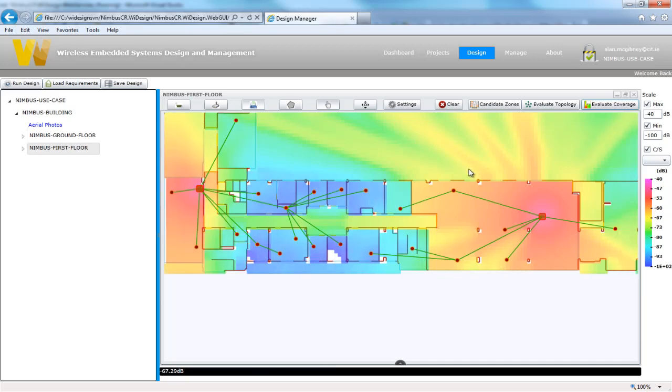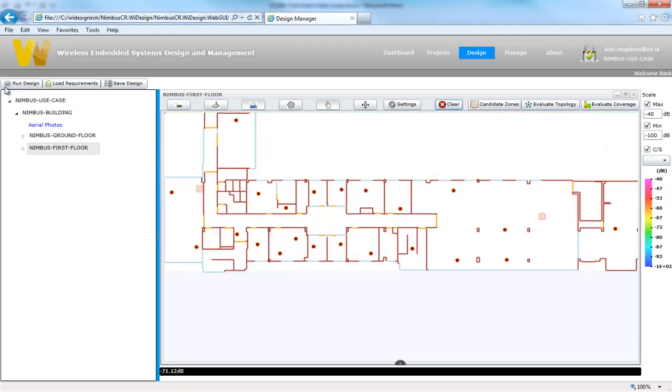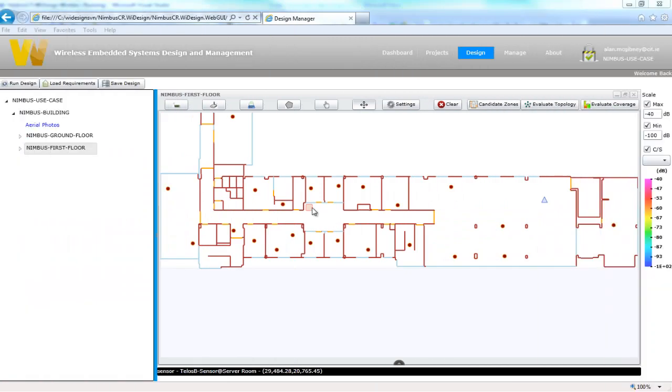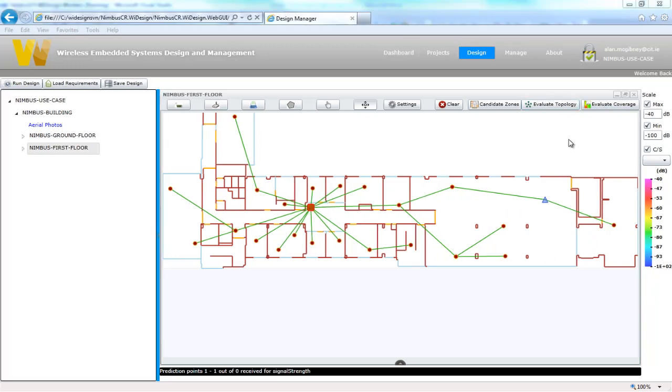Even with the tool, manual tuning of device placement can be a difficult process, especially if the environment is large. Therefore, the Wireless Deployment Planning tool provides an automated device placement algorithm which will optimize the number and position of gateway and repeater devices driven by the placement constraints defined by the user. In this example, the results of the optimization process propose that a single gateway and the addition of one repeater is sufficient to ensure all nodes are connected in this floor plan. The automated approach of the tool minimizes the effort and expertise required by the user when planning their wireless sensor network for their building.